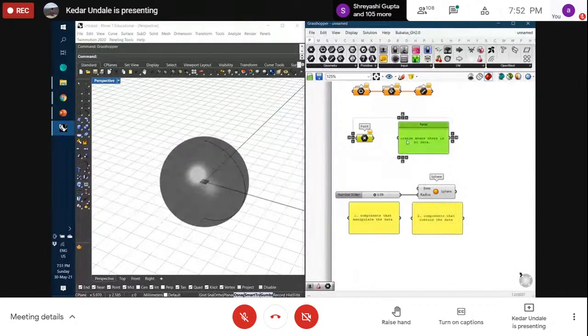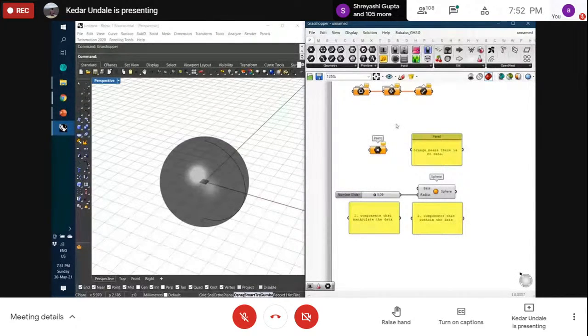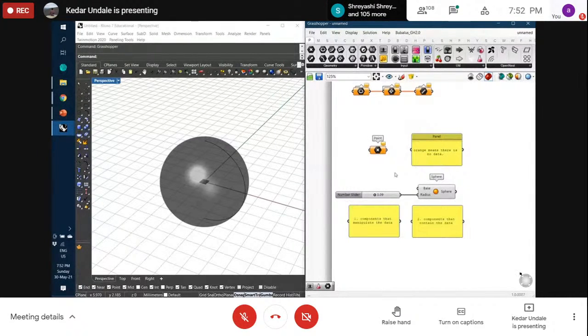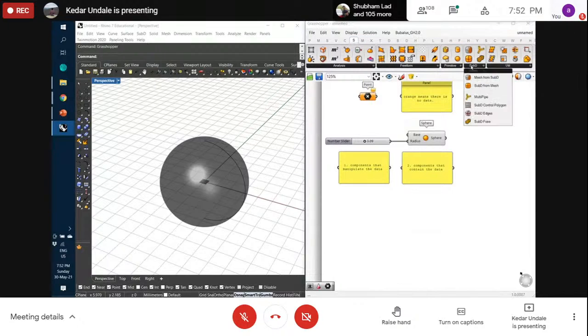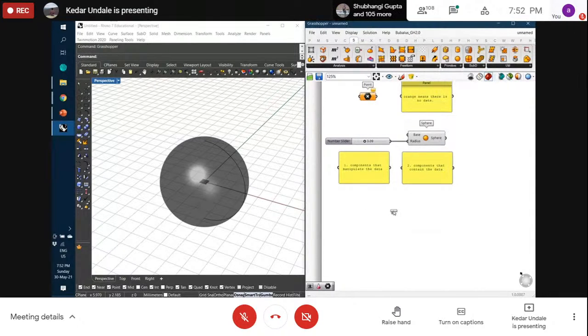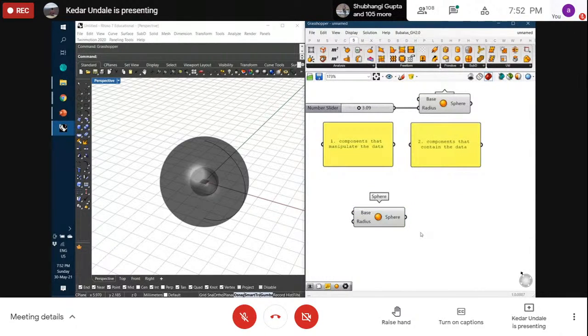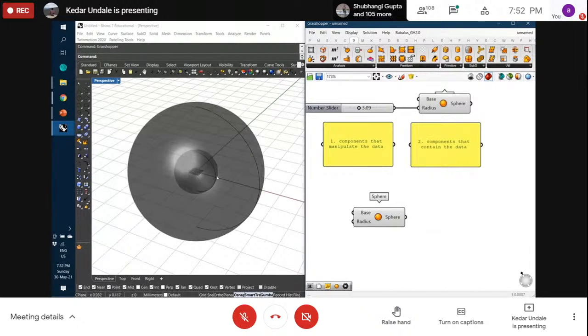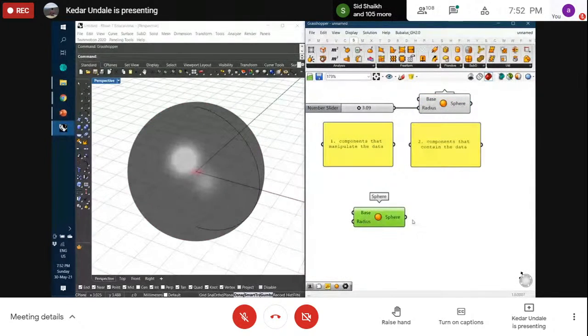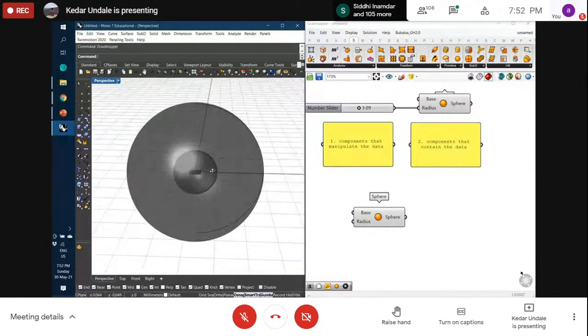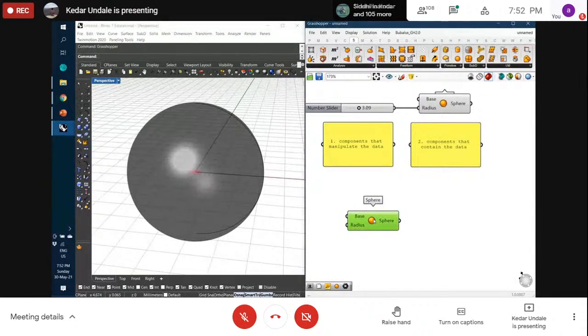So now we have seen this. Now I was telling you about another color, which is red. Red means error. Now where do I see this? Let's go again to surface, primitive, sphere. Now logically, you see that I can see sphere inside of sphere because this is one sphere and this is another sphere. That's why I like to add alpha value when it is normal, so I can see that there is another geometry inside it.